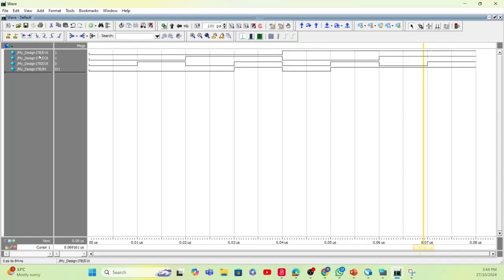This is difficult to see, so you can click this, yeah, toggle leaf name such that you can see only D1T, D2T, D3T, 80. You can see here 0, 0, 0, 0, 0, 1. So the output is 0, 0, 1, 0, and so on until you have 1, 1, 1, and the output A equal to 1. So you can see that we end the simulation at 0.08 microsecond or at 80 nanosecond exactly. All right. So this is based on our test code.